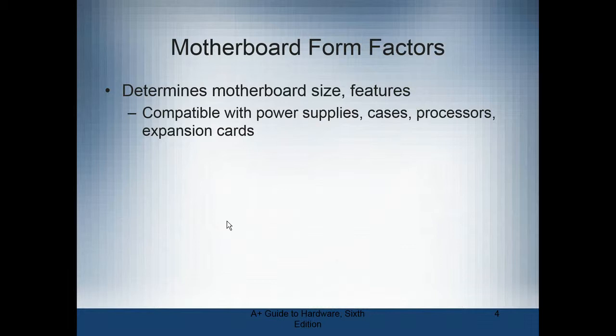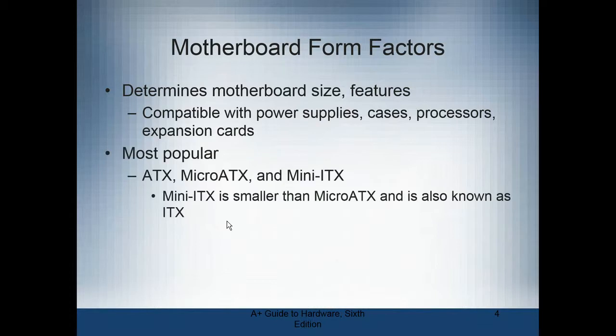Does the case support, and most cases actually support most motherboards. Many cases at least have multiple capabilities, and they'll be marked with what form factor where you put the standoffs in, the post standoffs in. I bought the case, ordered this motherboard, and the screw holes didn't line up. Screw holes didn't line up because the form factor was different from the case. The case didn't support that particular form factor. So that's one of the things that you do have to consider when you do these things.